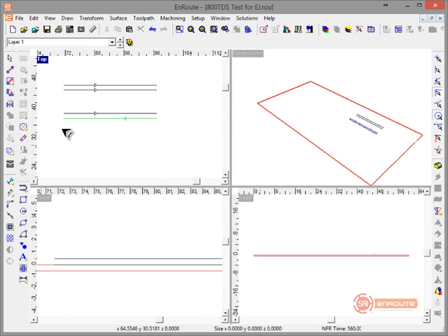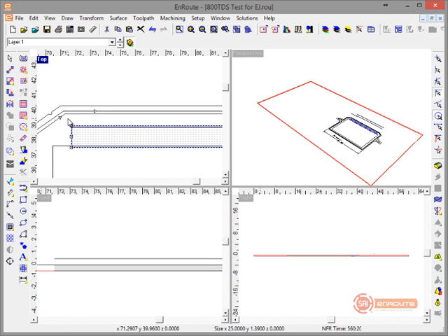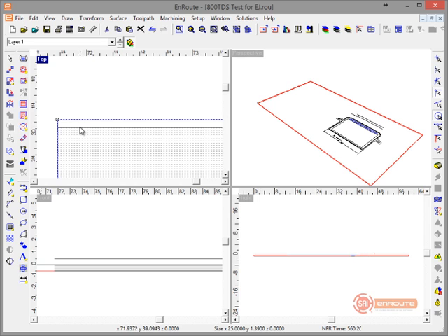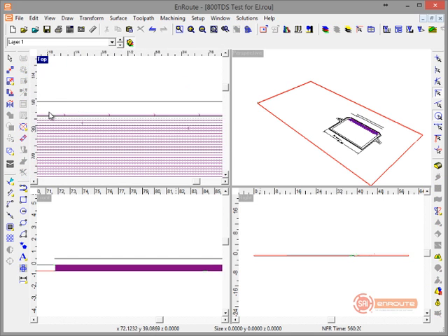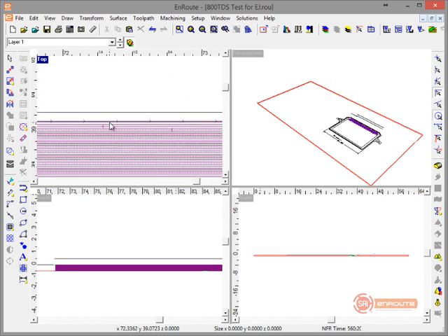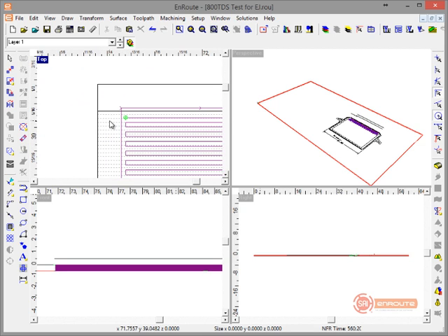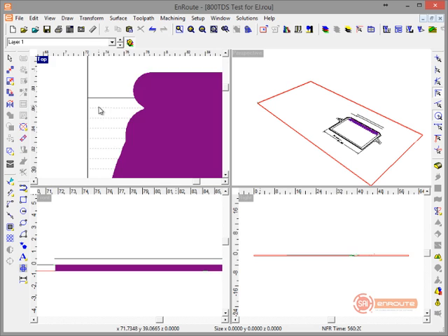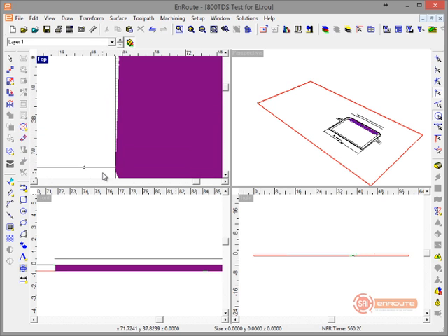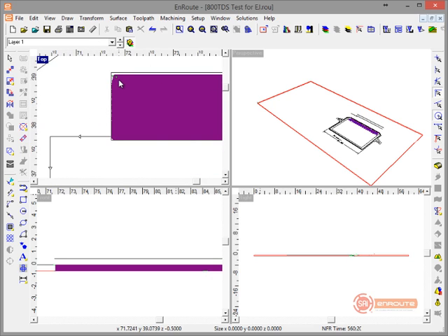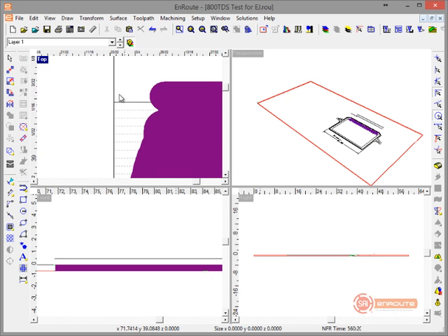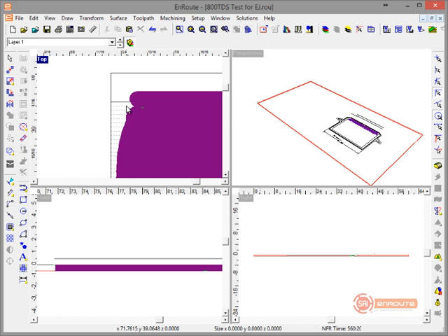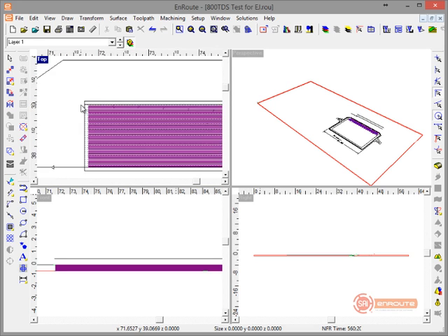And I'll do that same join contours. Like this part. Hold down my shift key and select that inside part. And we have the same toolpath we're going to apply. But by doing that, my toolpath should come all the way to the edge here, but not come past the edge here. And of course that little radius is going to show up from the top and the bottom as it raises. So this would be something to try now. It's possible by looking at this we might need to reconsider how that works, but I believe this would be how we want it to be.